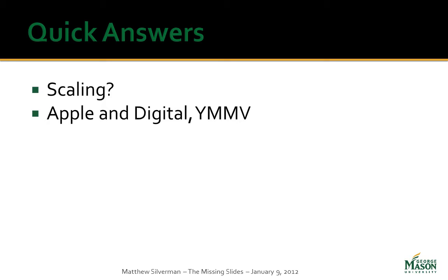And lately with the Thunderbolt laptops, we've had somewhat inconsistent results. In our lab testing, VGA worked fantastically. However, for some of our faculty, it did not. We did tweak some EDID settings, and this was specific to Crestron. We had been using the copy projector. We went from copy projector to setting up our own manual tables. One of the things we did find working with Apple is that Apple does not like Crestron's auto nor its copy projector. We found building manual tables was the way to go to best support Apple products.